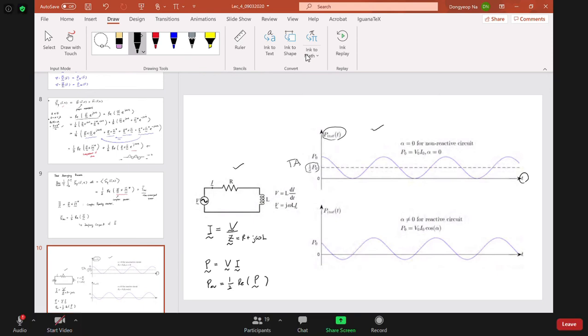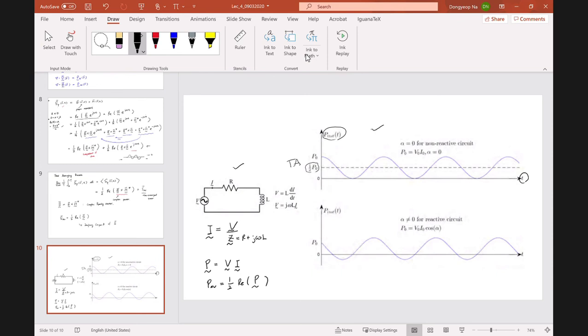On the other hand, if we have inductance, so that the voltage and current are out of phase, with a phase delay, then if we calculate the complex power, and from it the instantaneous power, over some time it takes a positive value, but it can also take a negative value.